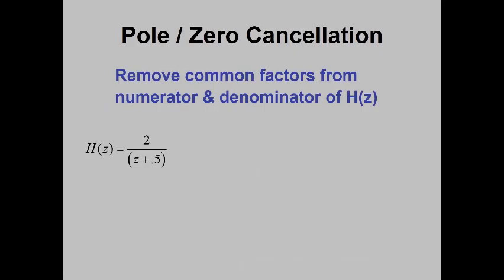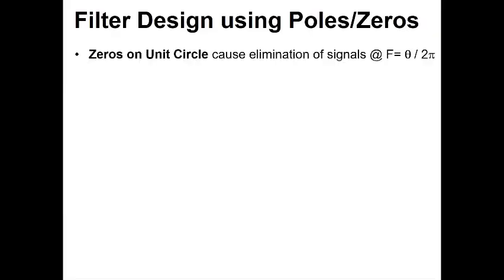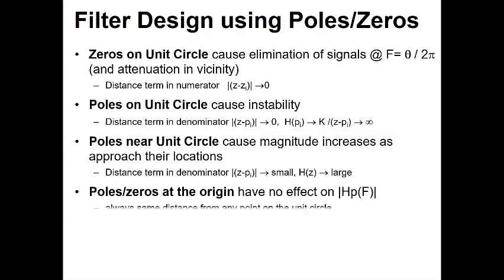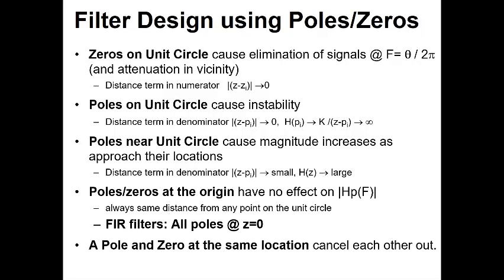Now, that's actually a design method if you have an undesirable pole in your system somewhere. You can design a 0 to sit on top of it and eliminate it. It's actually more reliably done in discrete time systems, if the origin of that pole happens to be something in a discrete time design, not in some analog component.